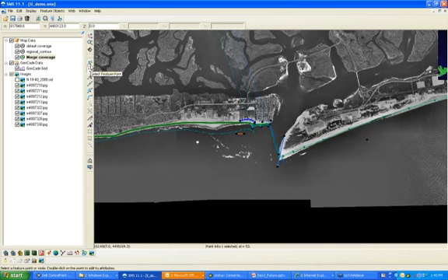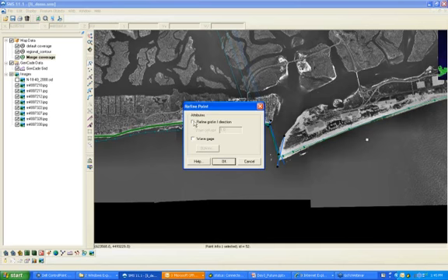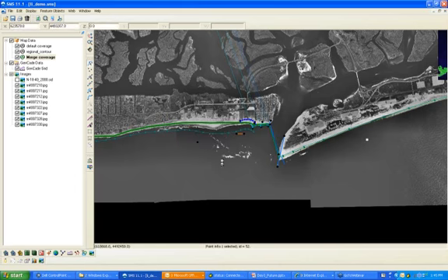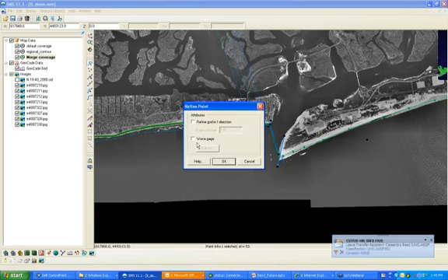Then I'm going to go to Select Feature Point. I'm going to click, and instead of having a wave gauge, this is going to be your refine point. I'm going to specify the base cell as 50, and then hit OK. I'm going to do the same thing on this side. So I'm going to double click. I'm going to go to Refine Grid in the I direction, and I'm also going to say 50.